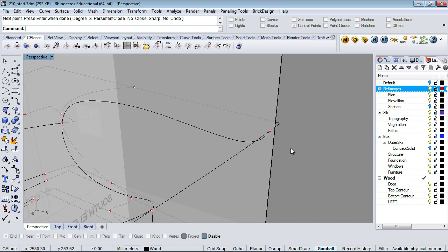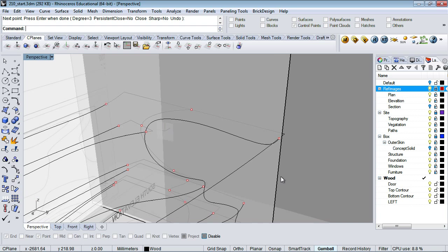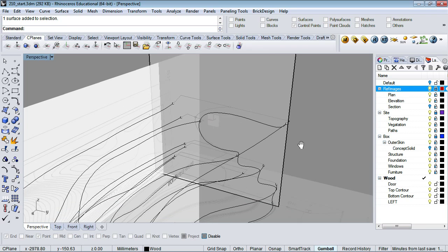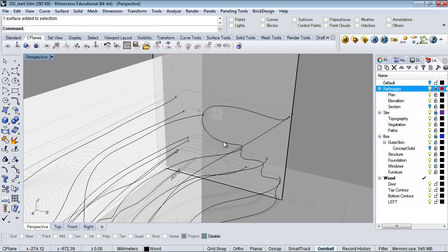Okay. So you notice that even though I said that I was only really concerned about going to this curve, I drew the whole curve. And so what that allows me to do is to arbitrarily split this curve someplace so that I can then start and control the section. So I have some guide point in terms of tangency of what I want it to look like when I do this blend surface. So I have kind of a reference there. I just find that it's a little harder to kind of stop and then restart again.